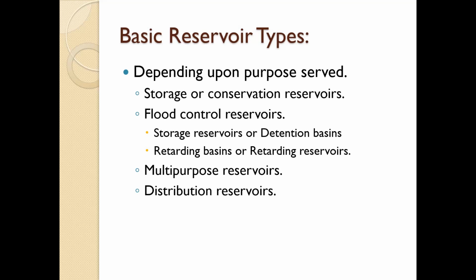Such reservoirs are therefore helpful in permitting the pumps or water treatment plants to work at a uniform rate, and they store more water during the hours of no demand or less demand and supply water from their storage during the critical periods of maximum demand.